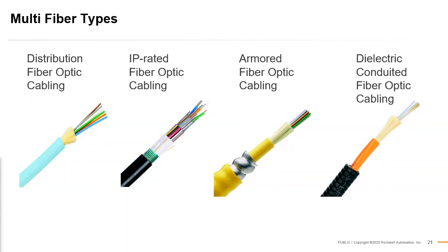There are benefits, like armored fiber optic gives you the ability to not require conduit. But we also sometimes have additional requirements with explosion proof environments and such, where we have to have a seal that can't just be a flexible individual piece.